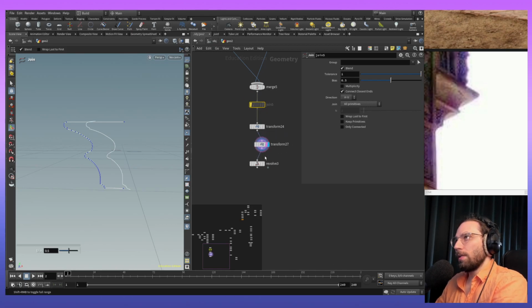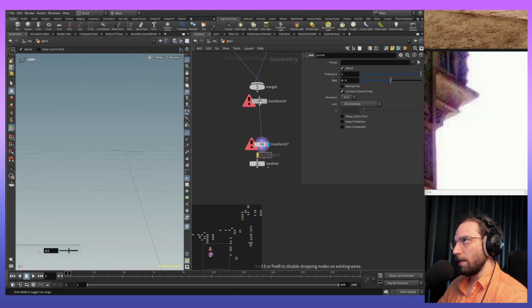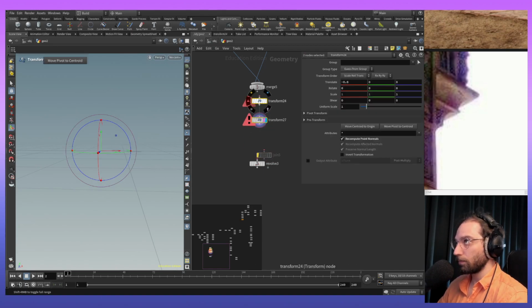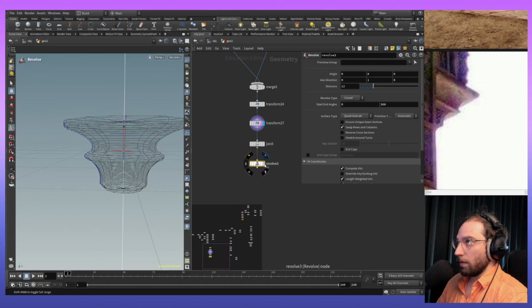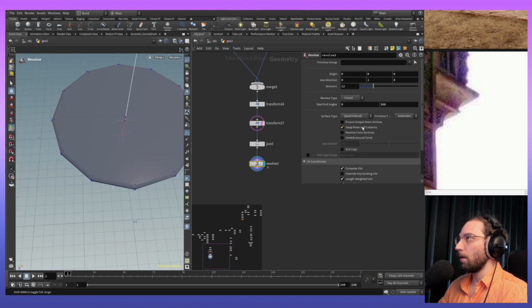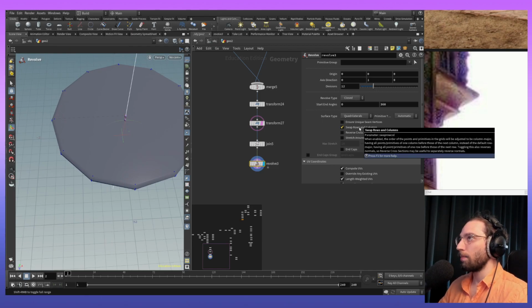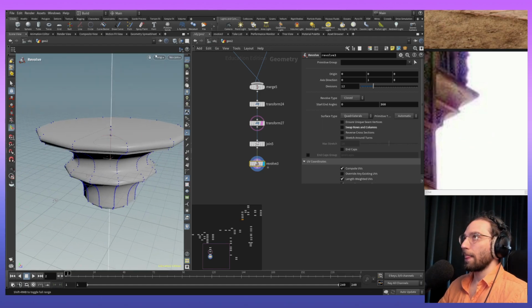So what we will do is disconnect this from the revolve, and the join, also disconnect that one. Take the join maybe beneath the transform values, and see if that changes our last results, because the faces were flipped. And now we put it into the revolve and see, yeah, it's better. It is looking better. However, we need to uncheck swap rows, and now we have it unflipped again. Good stuff, guys. We will add the flat shade.